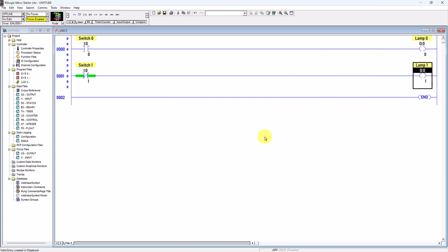Okay, so usually for this simple circuit, we switch on the external switch, which is for example normally open, so the current will flow through the circuit to energize the digital input 0 or terminal point 0, and this will cause the virtual switch to trigger from normally open to close.